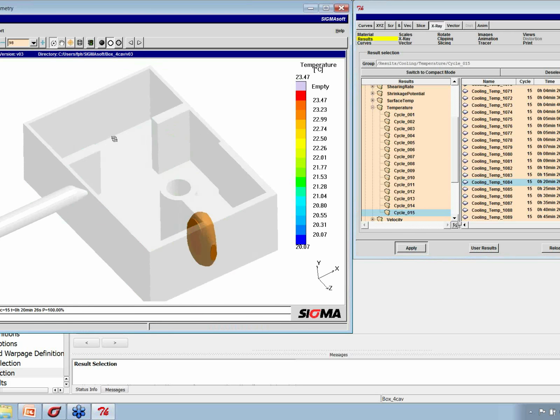All right, so at 20 minutes, really now we just have this one area here. So we're still getting additional shrinkage, additional displacement, stresses are changing in that area. And as I showed earlier, our crystallization has actually stopped. Go to 25 minutes, and boom. Now everything is completely cooled to room temperature.